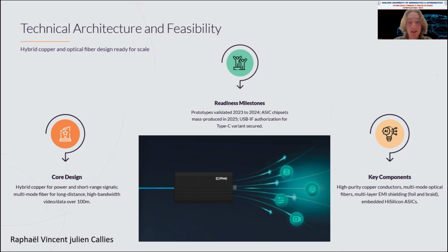The core of the design is a hybrid approach. It strategically uses copper wires to handle power delivery and short-range signals, while dedicated multi-mode optical fibers are employed to carry high bandwidth video and data over long distances, with reliability exceeding 100 meters.